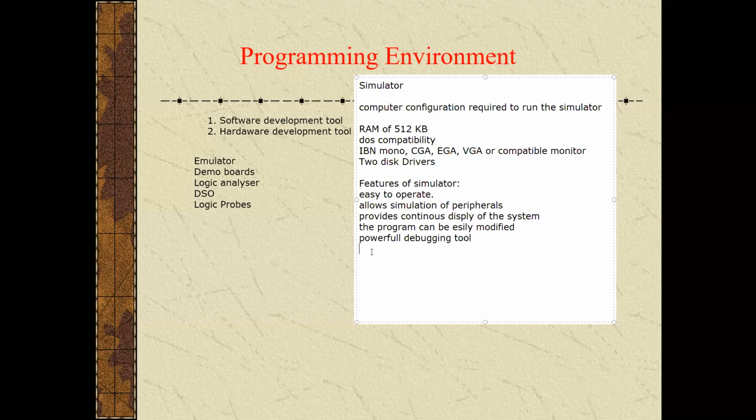The content of any location in the code ROM, the internal RAM and the external memory can be changed as the program executes. The IO ports may be simulated by changing the value of the port SFR, and interrupts are simulated by striking a function key on the keyboard.